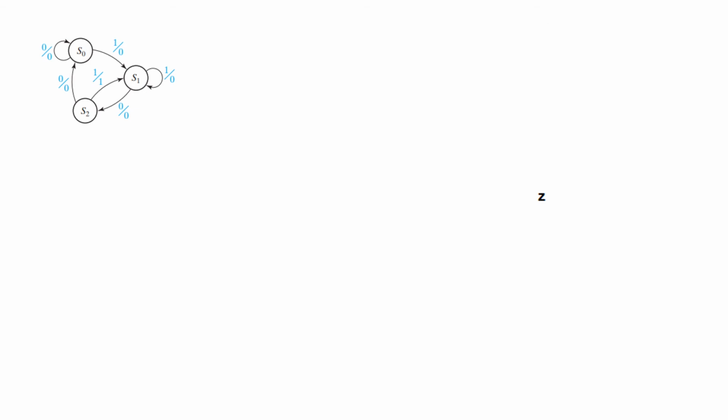So now that we have drawn the state diagram, let's move into incorporating flip-flops, because that is what we need for designing the circuit. And a flip-flop design could be something like this, not exactly this, but we'll have two flip-flops because there are three states here. So at least two flip-flops we need, or exactly two flip-flops we need.